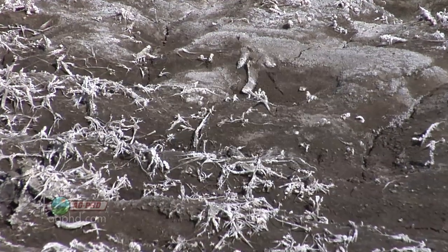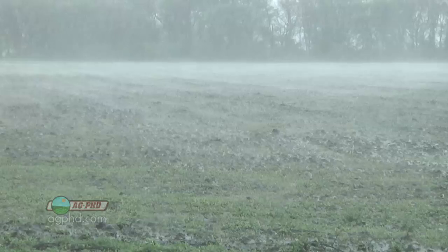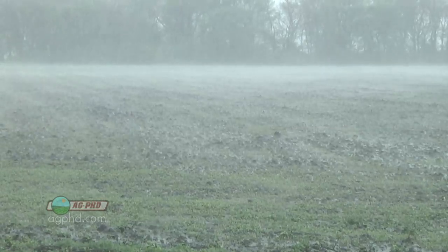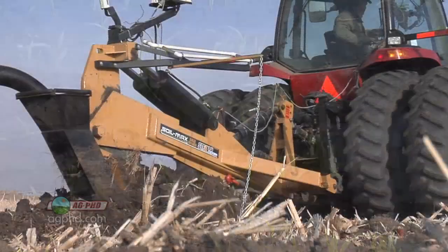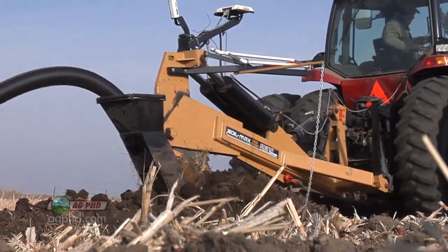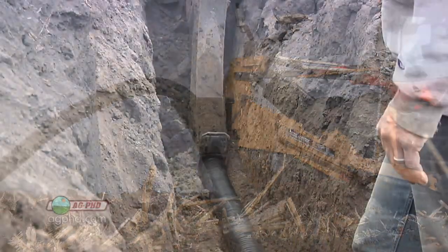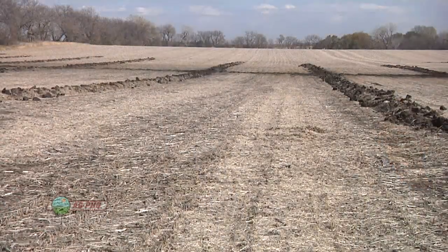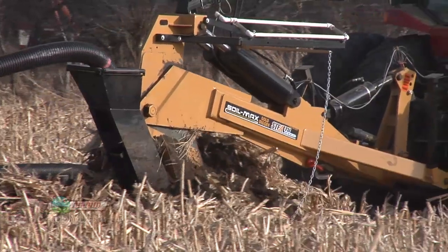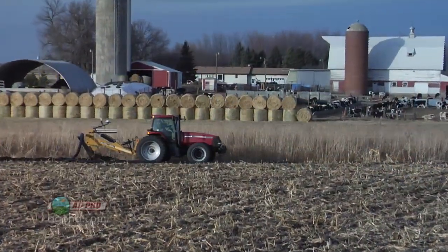Well, here's the good news. Salts are leachable. In other words, they're going to flush out with water. So just think about it. All you have to do in those poorly drained spots is improve the drainage. Put some tile out there 3 feet down in the ground, maybe even 2 feet, maybe you have to be really shallow, 2.5 feet, I don't know, and have a bunch of lines. My point is, if you get some tile out there and the water can find that tile line, it's going to carry the salt right out of it.